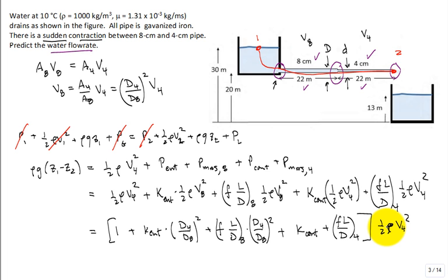Did that make sense? You follow that logic? Okay, so at this point, what I'd like to do is substitute some numbers, but to get the friction factor, what friction factor do I use? Almost anything close will work. A friction factor between 0.02 and 0.04 will work, somewhere in that range. 0.03, run with it. You do 1 iteration, 2 iterations, you're going to zoom in real fast. Prove it to yourself by doing that.